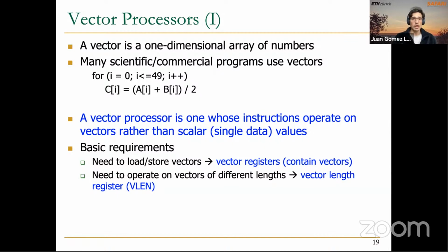But maybe we can also have an intermediate software layer, and we could define a longer vector length, like for example 50, right? And how are we going to operate on these 50 elements using 4 processing elements? We will go 4 by 4, right? So if we have 40, we will need 10 iterations, right?